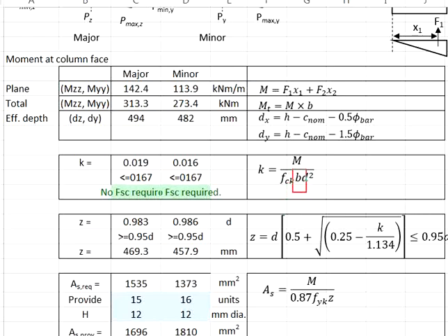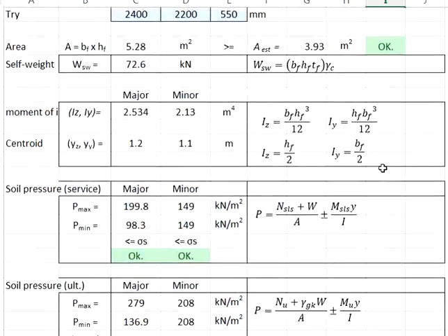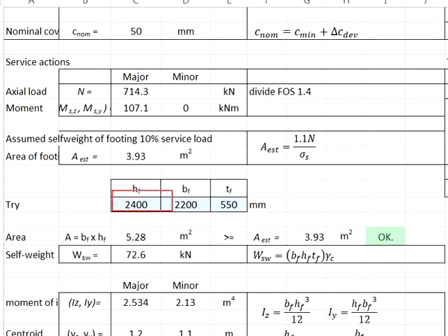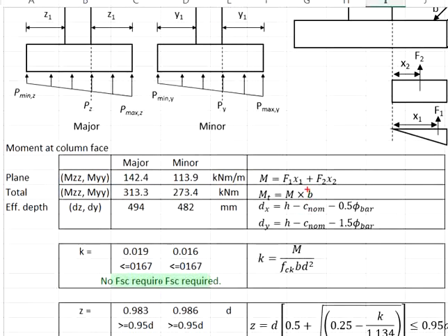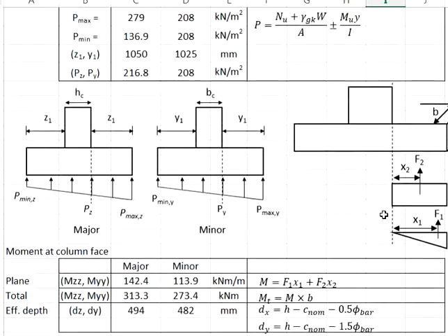If you have difficulty identifying which B is to be used, since they are of different values, always sketch. Through these sketches, you determine which B is to be used. Let's say you are dealing with the major axis. Sketch the pad footing in the major axis.